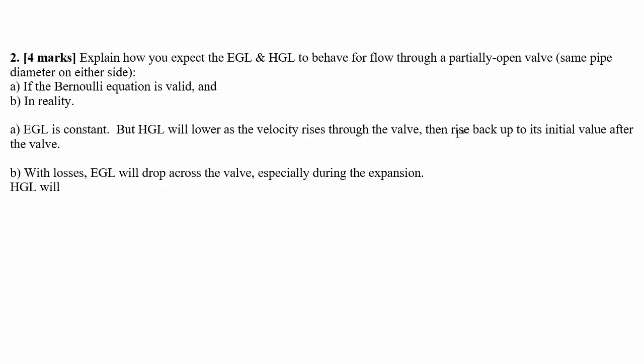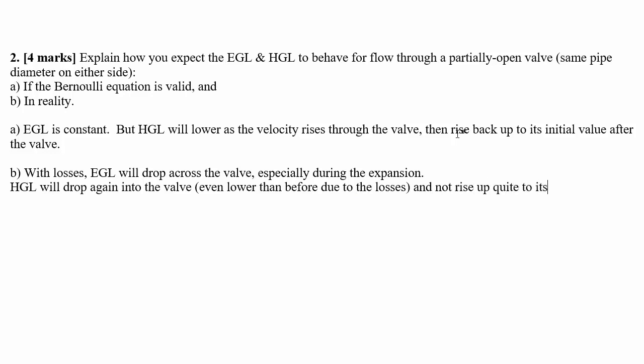For HGL, it will drop again into the valve, even lower than before, due to the losses, and not rise up quite to its initial level. The difference being equal to the drop in EGL.